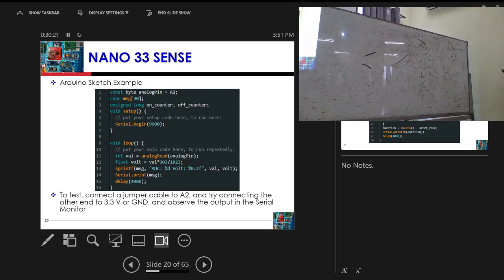So I do that, and then once I use sprintf, I can use this entire thing: sprintf, msg, ADC, this. All of these values will be stored in the message, and then I can come and use Serial.print and print msg, and you just print the ADC colon, then the voltage. So instead of using 4 lines of code, I can use this one line to print everything. But I cannot use Serial.print and do this. It will give me an error.